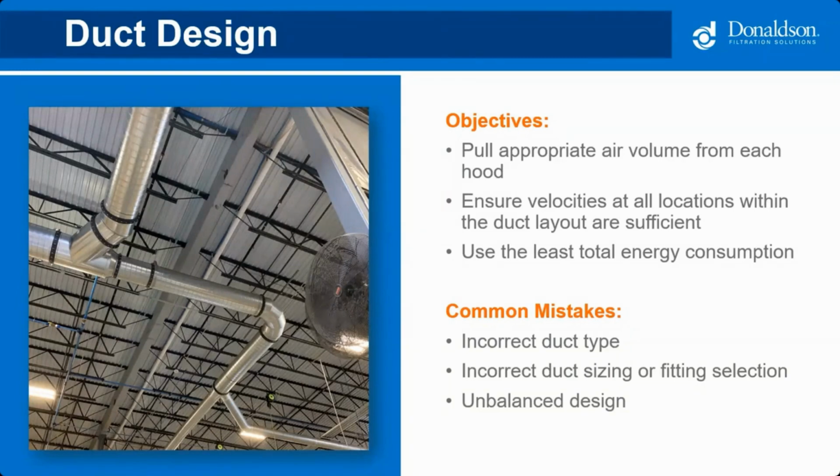A few common mistakes that we see when it comes to duct design are the incorrect type of ducting that is being used, the incorrect duct size or fitting being used, and the duct system not being balanced correctly.